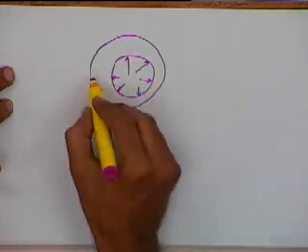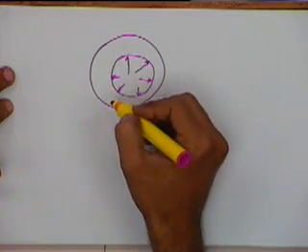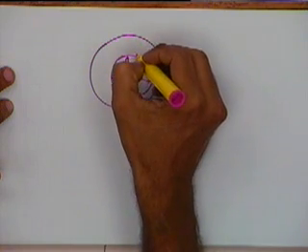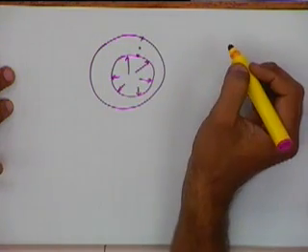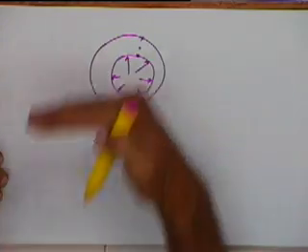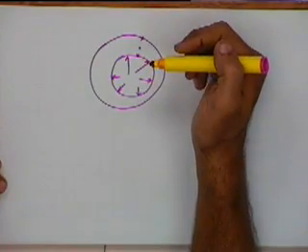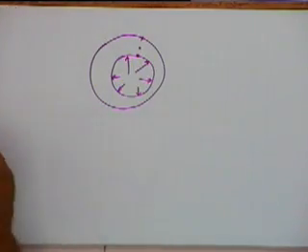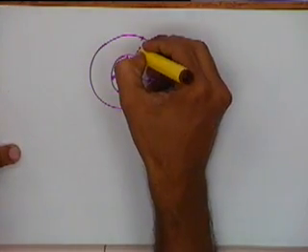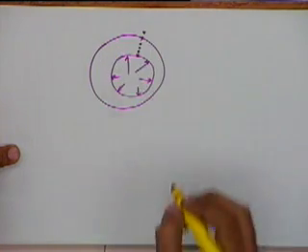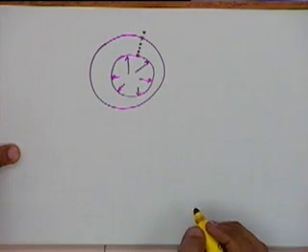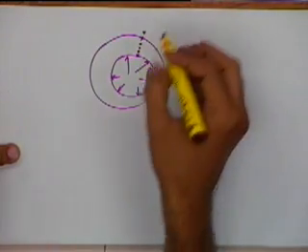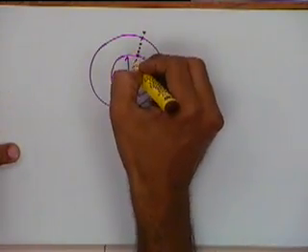In this case, since I am assuming a uniform thickness and the pressure is also uniform, if I have nodes here like this, the nodes are all going to move radially outwards. Okay, so this node will get deflected maybe to this position and this position respectively. But all these nodes should be moving radially outwards.